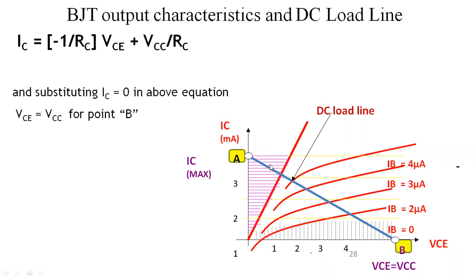this is the saturation region, where the transistor is in saturation and maximum current is going to flow, and we will get the maximum current at the output. And when it is in the cutoff region, there will be no current and no voltage at the output, at the collector. While the remaining region of yellow lines or these red lines indicates the active region.